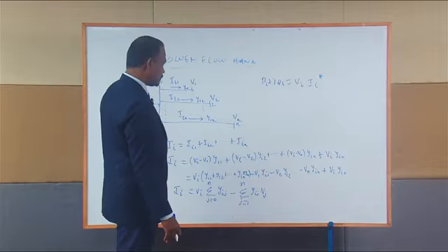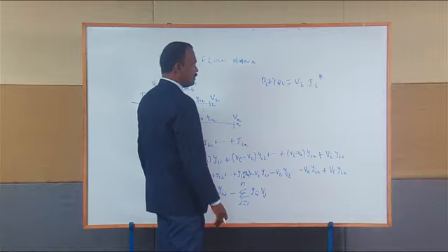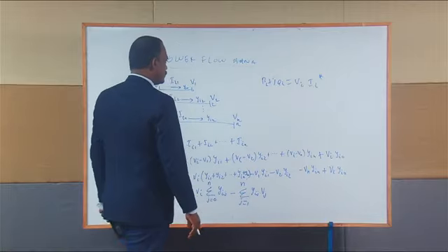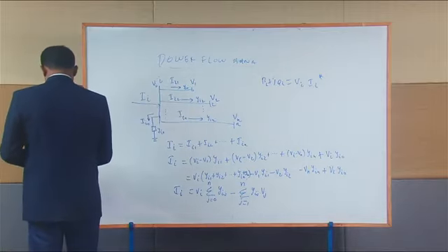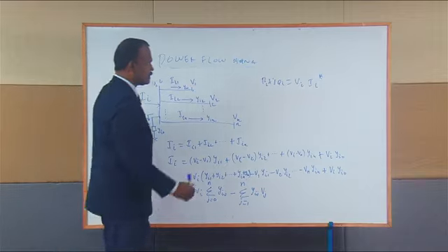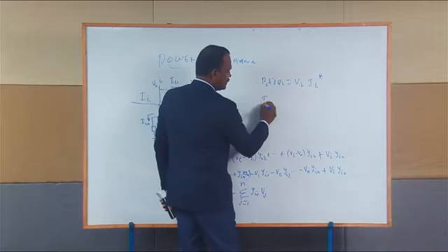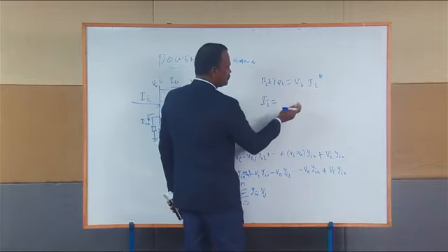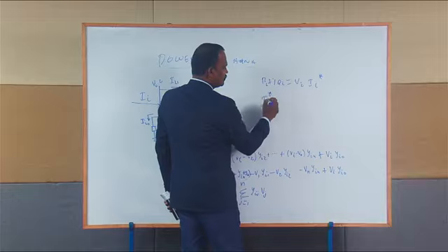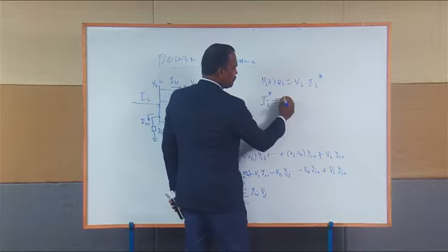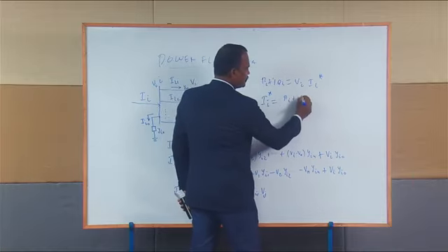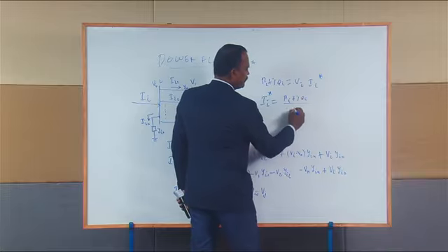Now in this equation I want to find the expression for Ii. Ii conjugate is equal to (Pi plus jQi) by Vi.